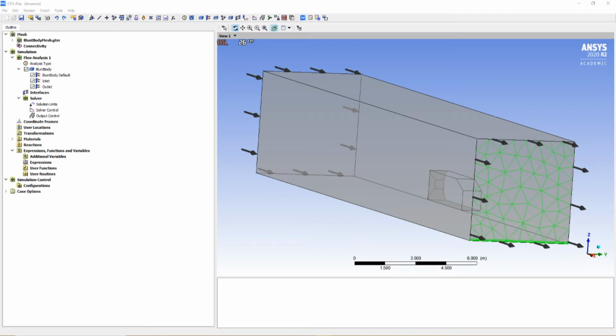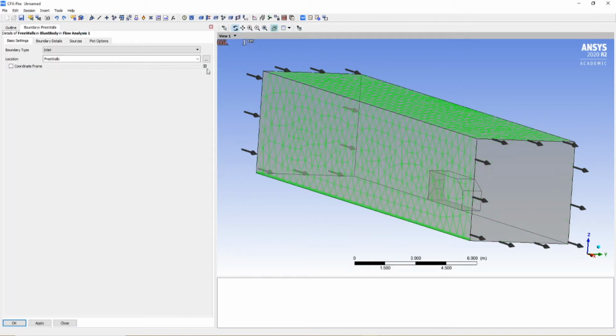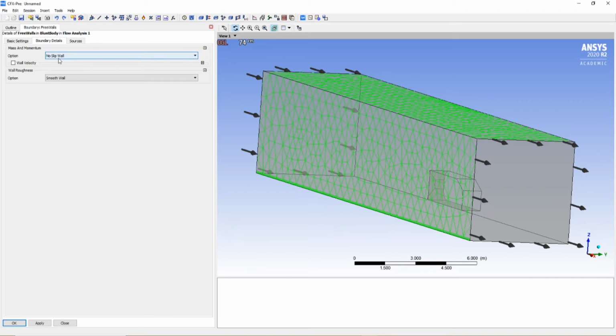So we're going to apply a single boundary to both walls by using the composite region that we created before. Let's create another boundary condition. This time we're going to name it free walls, and it's already set up to the composite region that we created. But we're going to change the boundary type from inlet to wall, and we're gonna go here in boundary type, and this is what I was saying about the default condition.